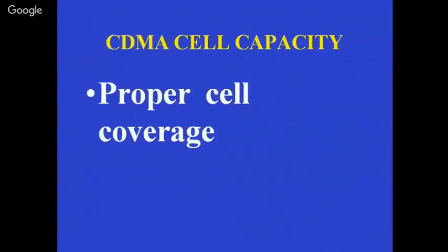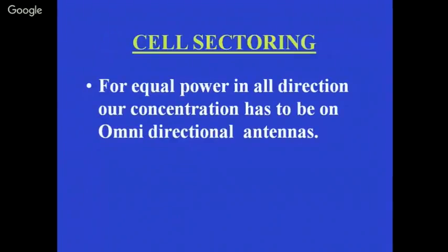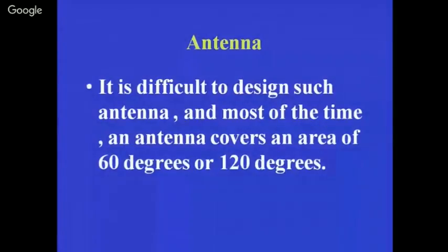CDMA does not make such clusters. In CDMA, there is only one channel, and on that one channel you put different codes. So there is no question of making such clusters. So what do they do? They either split the antenna or make a directional antenna or something different. Different types of techniques they will use.